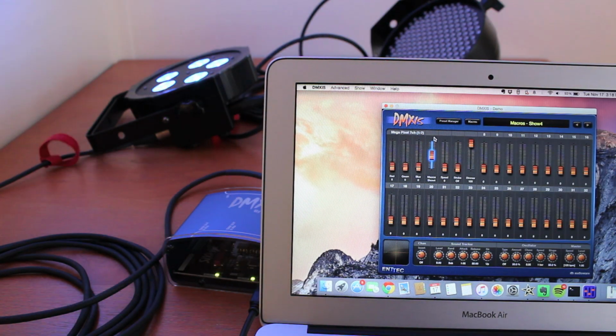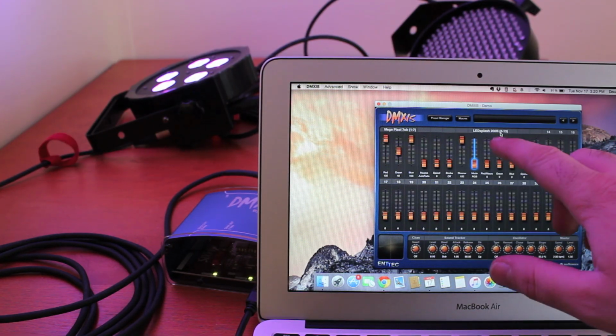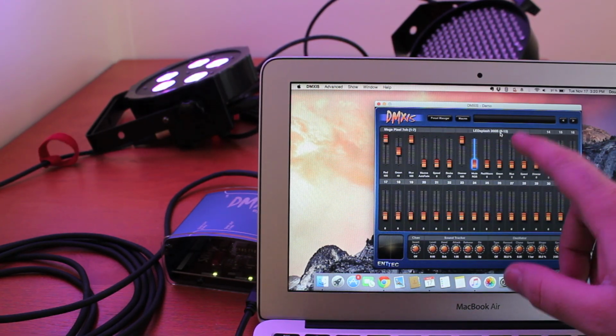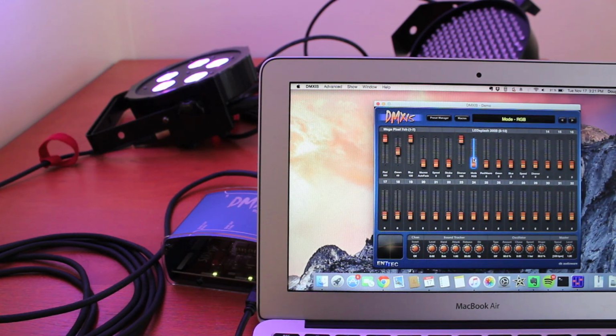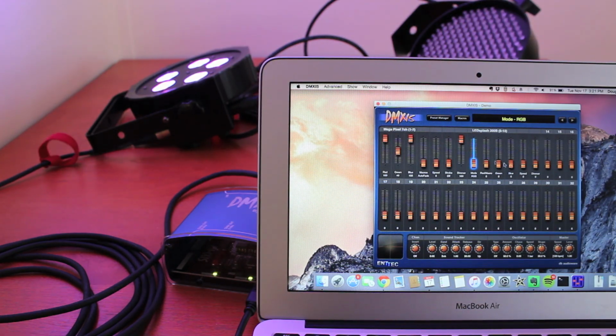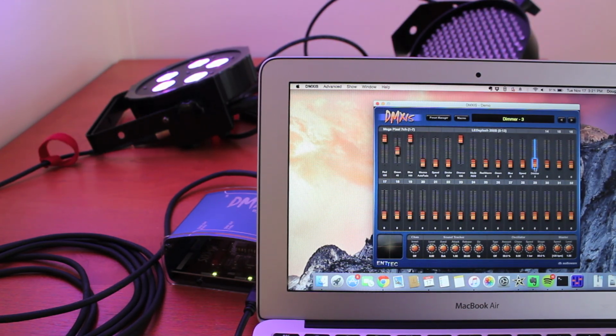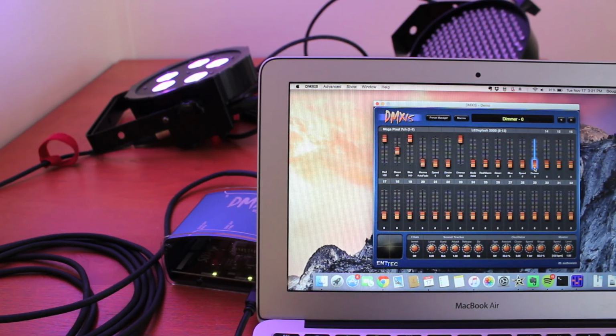And we can go into different presets. What I've done is I've loaded up the preset for the LED Splash 200B. This is a 6-channel light. The first channel of the light, which is going to be channel 8 in our DMX map, is mode RGB. So this is various modes that are built into the light. We're going to leave that one. This does have a dimmer, but on the Chauvet lights, it works opposite of the American DJ. So dimmer needs to be at 0, and that is full strength. If we went to 100, that would be faded all the way out.